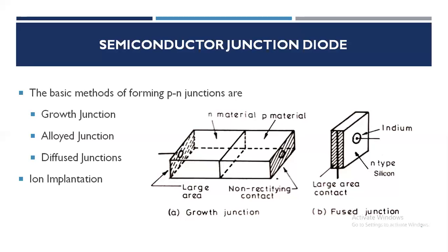Let's see ion implantation. A useful alternative to high temperature diffusion is the direct implantation of energetic ions into the semiconductor. The process can be done at low temperature in an ion implanter. It is possible to implant impurities which do not diffuse conveniently into the semiconductors.